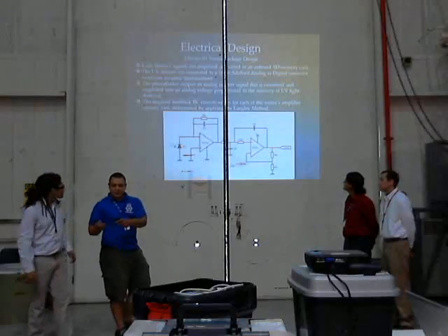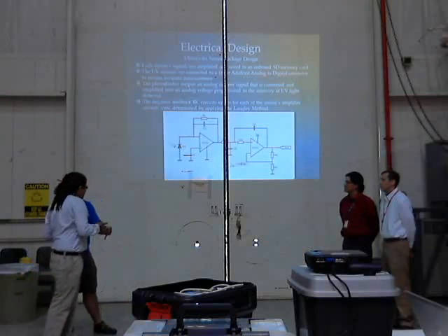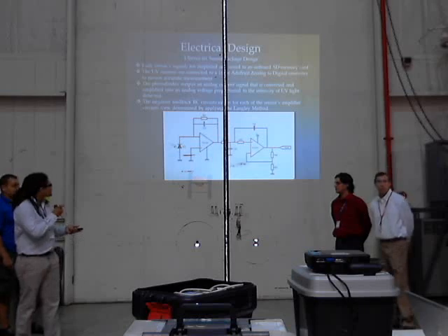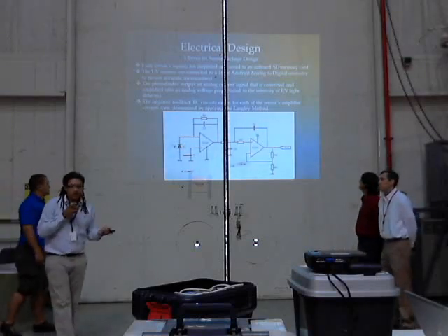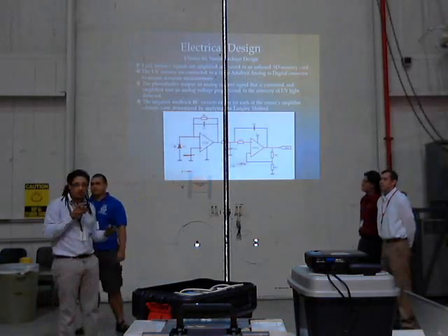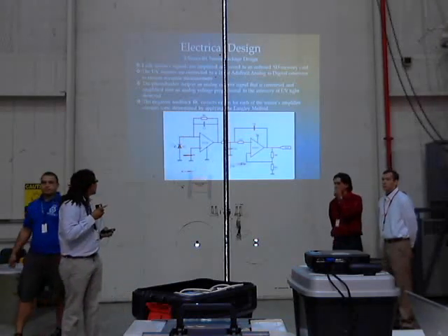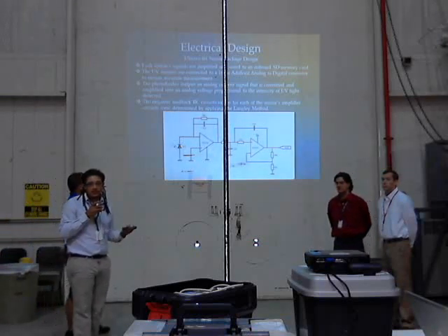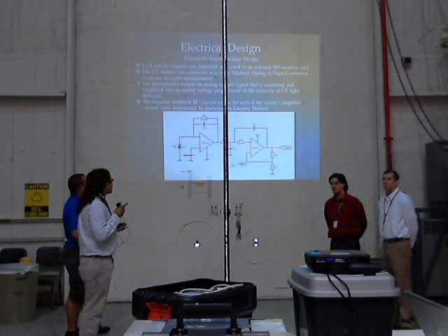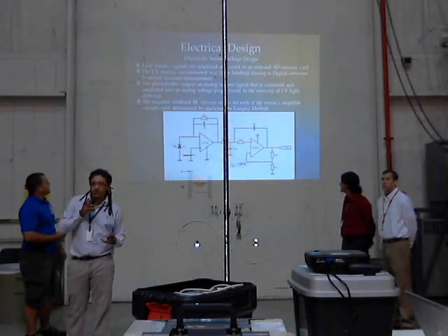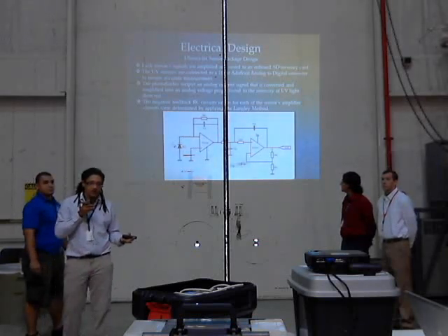Okay, now we'll get into electronics. For the UV sensor package, we have an onboard SD data logger. We basically use 2, one for each project. The UV sensors are connected to the Adafruit 16-bit A to D, so that we can get a more accurate measurement than the onboard A to D, which is 10 bits on the Arduino.